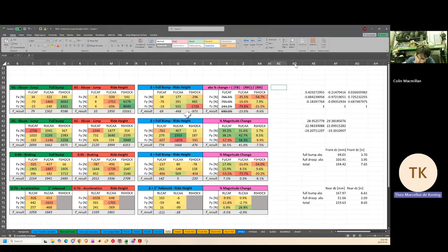The other thing to consider here is all of this calculation assumes that the forces are happening when the vehicle is level. We do have the load transfer calculation between front and rear based on the acceleration. But the calculation for the link forces themselves occurs at ride height, with the contact patch being at ride height. So for this abuse jump, this is assuming the car is landing gracefully on all four tires on a flat surface, basically.